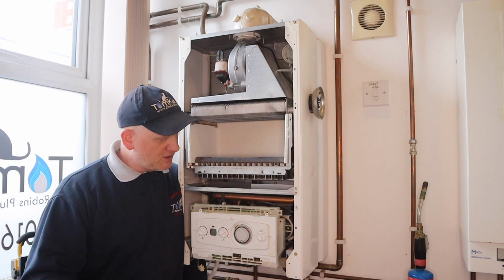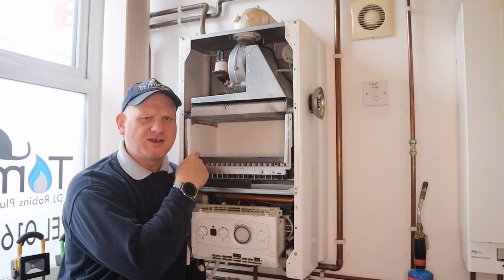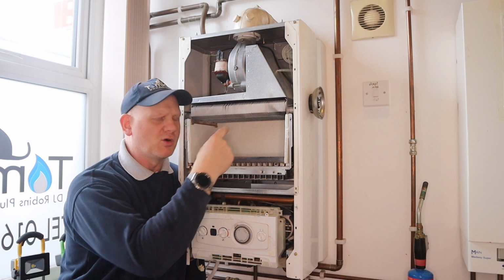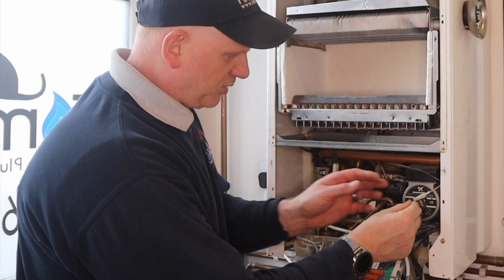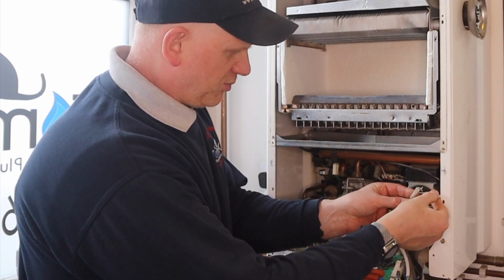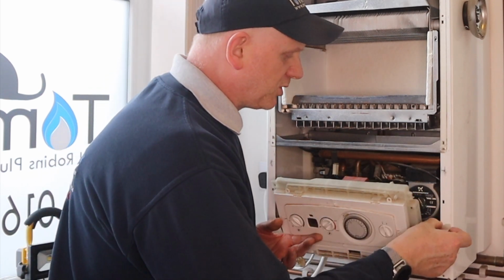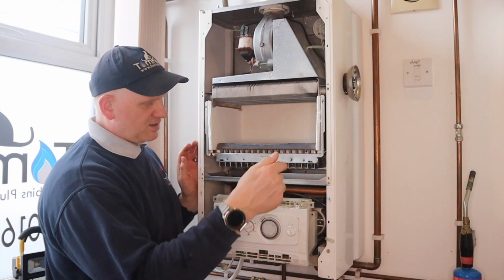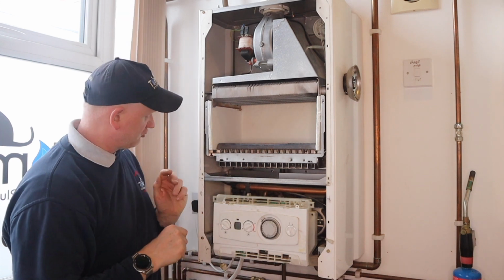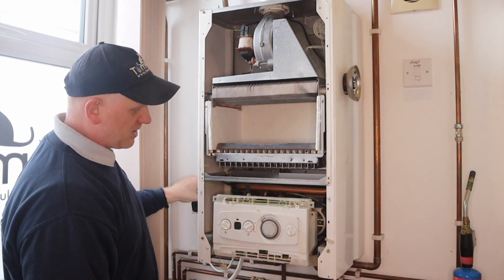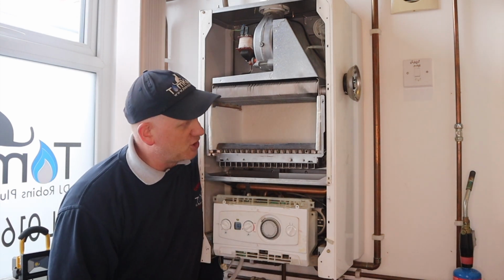So the last thing I want to look at in this video is what happens if the other end isn't working. So we've just seen if the ignition side isn't working, but what if flame rectification isn't working? So if I drop the flap down here, there is a little plug here, and if I undo that plug like that, and I put this back up, because that plug is linking the probe to the board. I've just checked it in the manufacturer's instructions and it is the right one. So I need to turn the power back on, I need to turn this back on, and of course it's going to go through its purge.